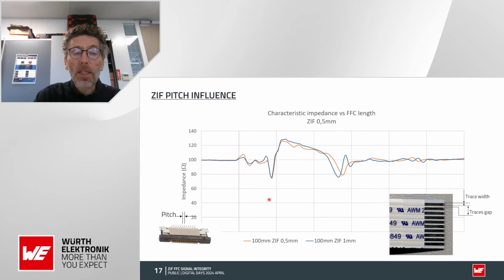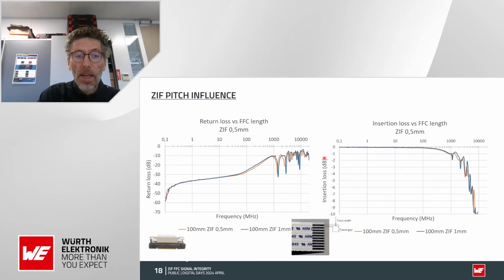Okay, now what is the influence of the pitch? You've got two curves of the impedance. The first one is for the pitch of 0.5. The second one is the pitch of 1 millimeter. You see that the impedance is really, really close, and the return loss, orange and blue, and the insertion loss are really close.